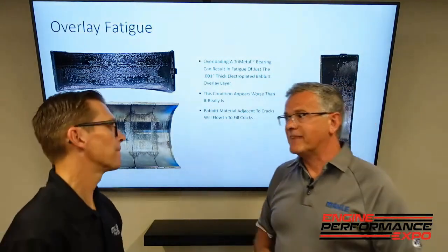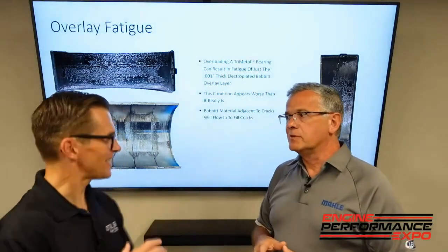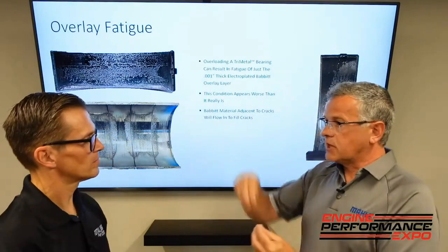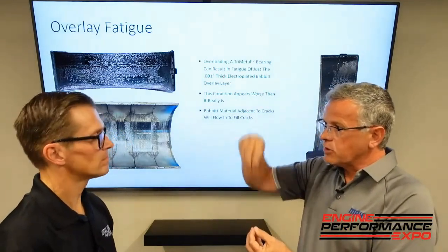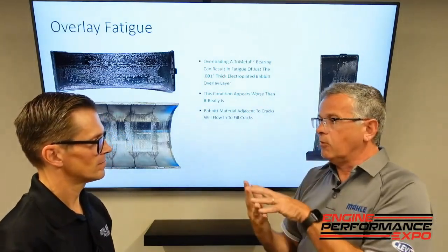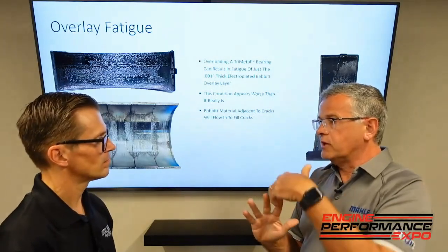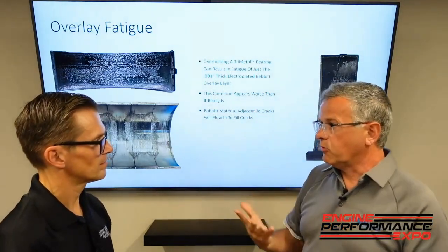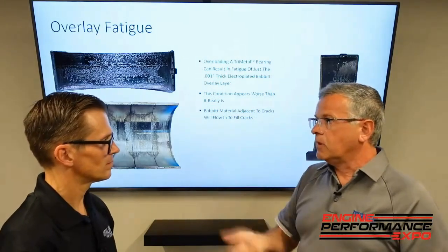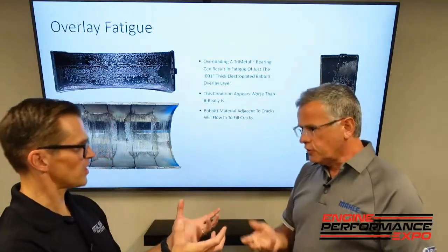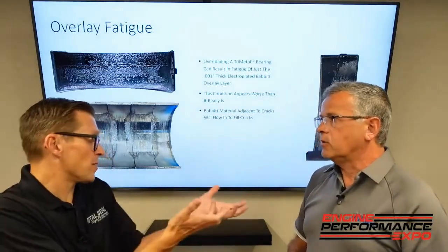Bronze. Yep. Exactly. The good old Bronze Age. So the lead helps as it creates crystals, bronze crystals, the lead helps soften those to give it some movement, and also, as we talked about earlier, foreign debris. It allows it to trap, embeddability is what we call that. So the grain structure is changing, giving it strength and some embeddability at the same time.